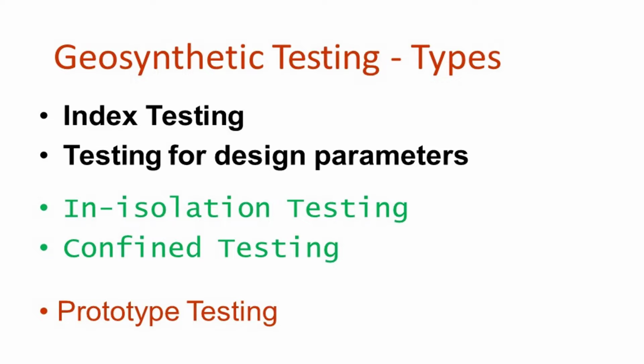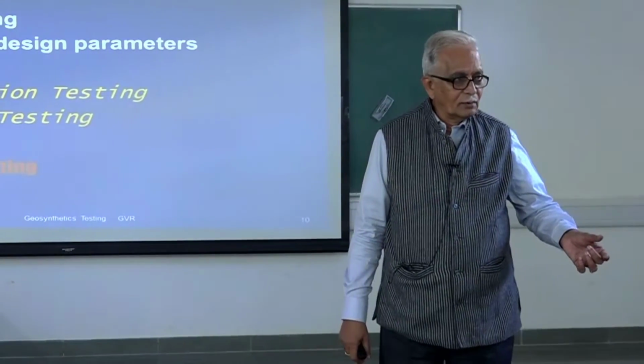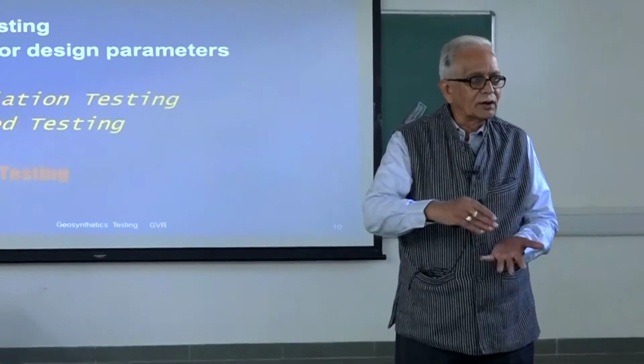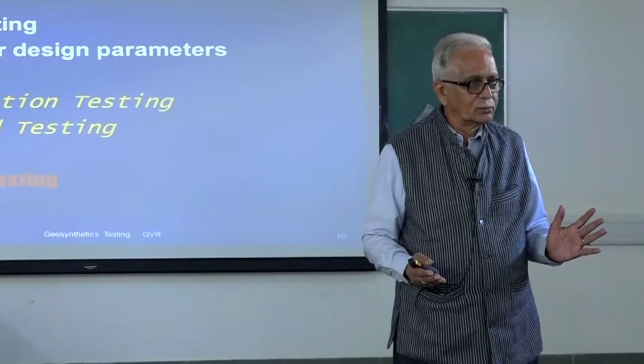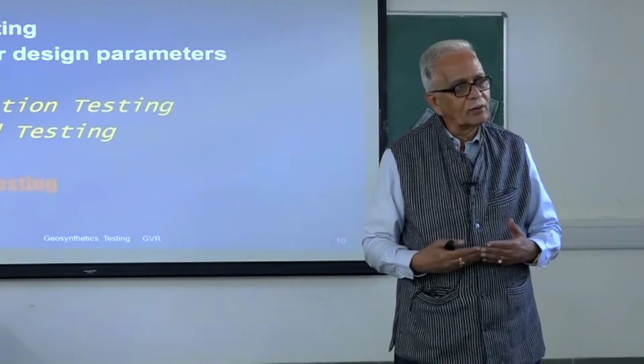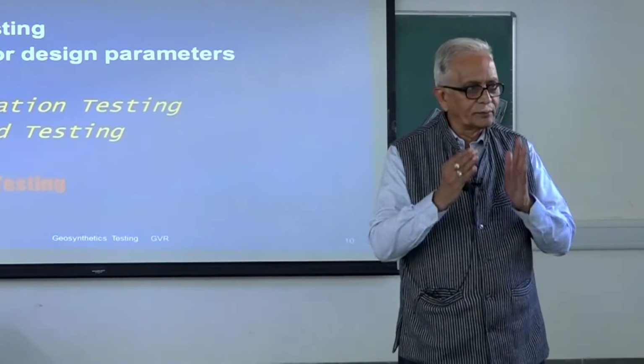And then also, a famous thing is testing in isolation. For example, we talk of hydraulic parameters. I can have this geotextile, put some loading on it, and allow flow of water along or across. Where is the soil here? There is no soil. Only the geotextile is used for testing.